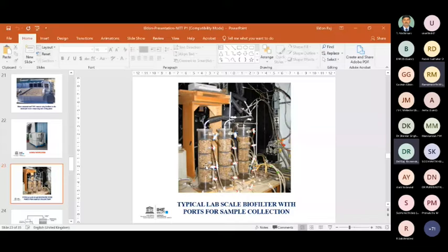So that is why I always insist that activated sludge is the best inoculum for inoculating biofilters as well as biotrickling filters. They have a host of aerobic as well as anaerobic consortia of microorganisms that can convert the waste gas into either methane or VFA or other products, as well as convert them into carbon dioxide and water.